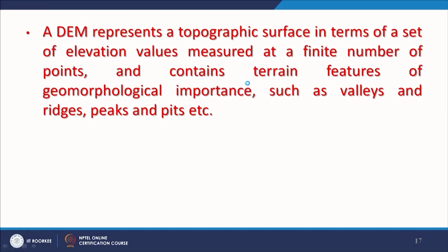let me very briefly introduce the DEM, which basically represents a topographic surface or terrain in terms of a set of elevation values which are measured at a finite number of points, not at every point, and then through interpolation techniques a surface is created.